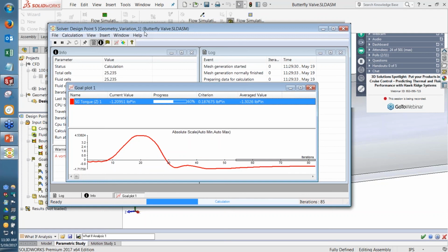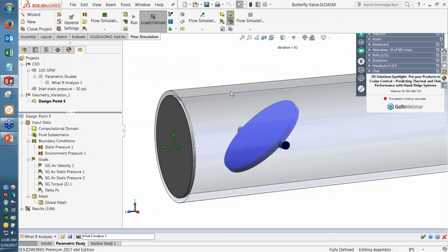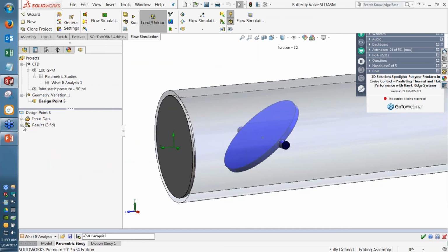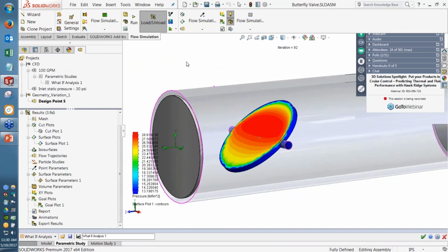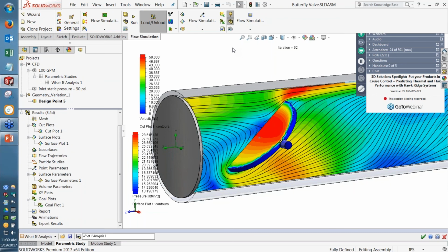Again, we're talking about the surface contours of pressure here, and of course all the velocities. Those pressure profiles on all the components are a load, and rather than guessing at the load for a stress analysis, they can simply be sent directly, again as a sequential operation. All it requires is you go to the Flow Simulation menu, Tools, and there's something called Export Results to Simulation. If we click that button, we're able to go over to the built-in SOLIDWORKS Simulation add-in, and I can create a new static analysis.